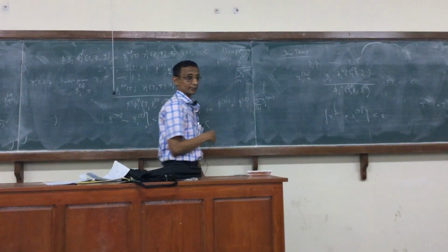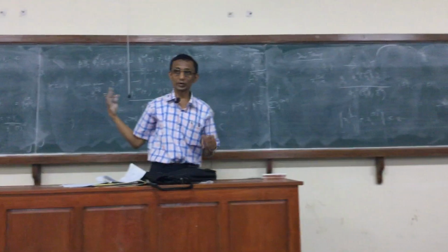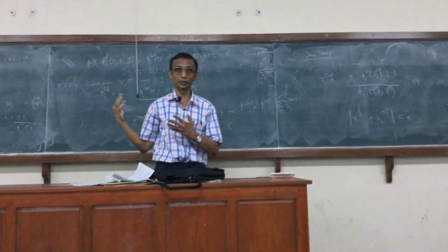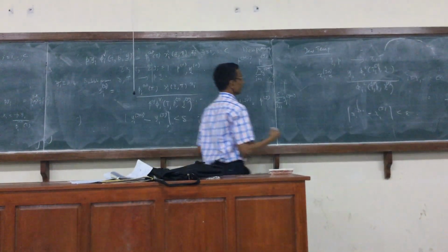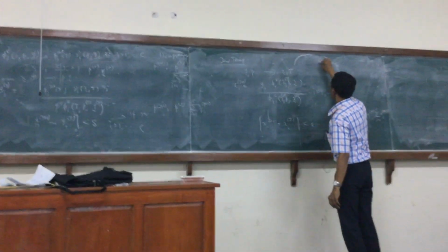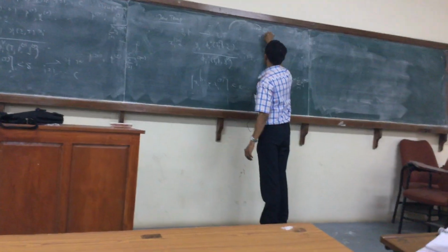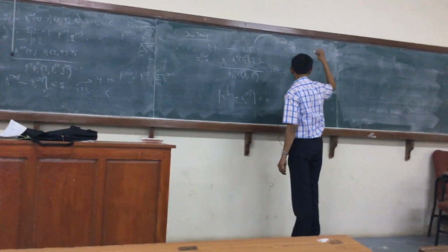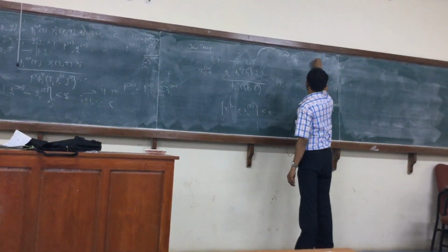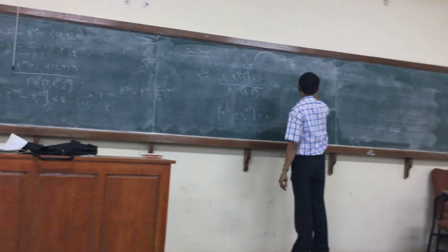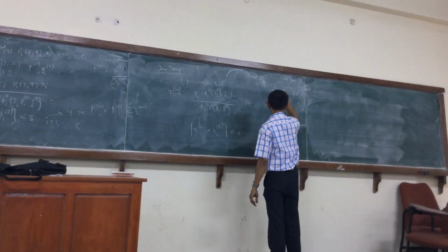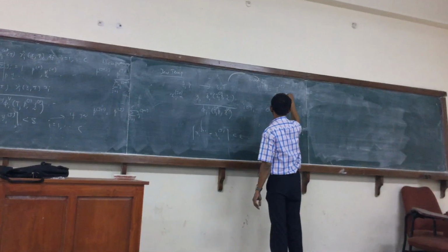You can check this, the same argument using the ideal equation, whether this is going to work or not. In the other case, the bubble temperature is probably going to be T j plus 1 is equal to T j divided by the sum over i equal to 1 to c of y i.